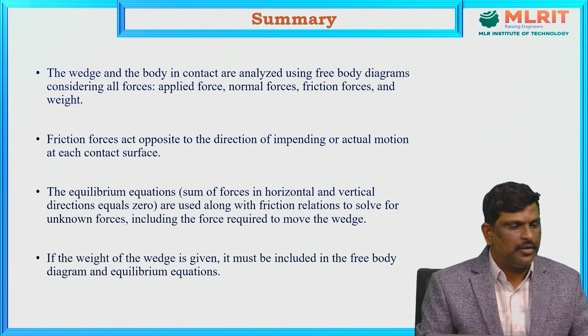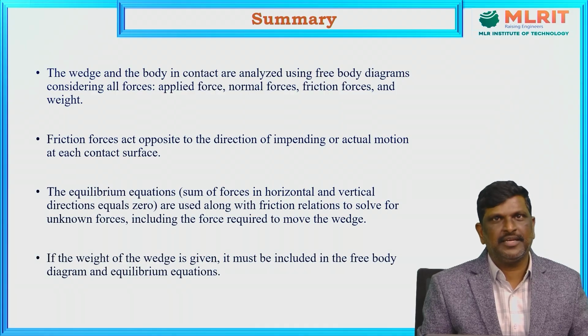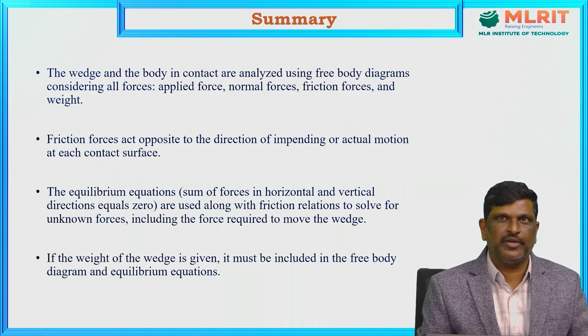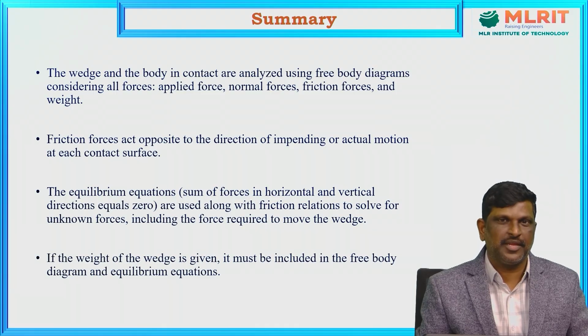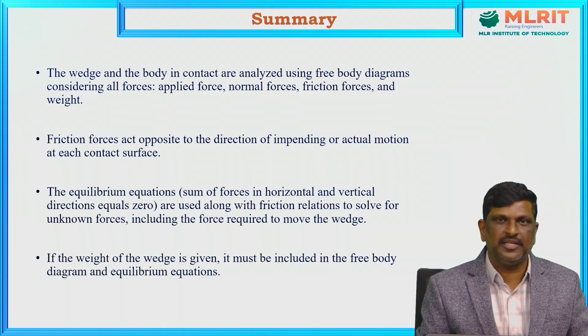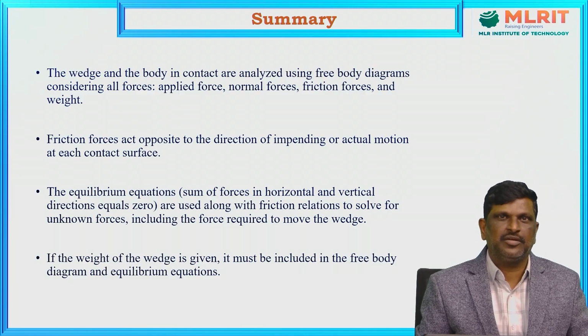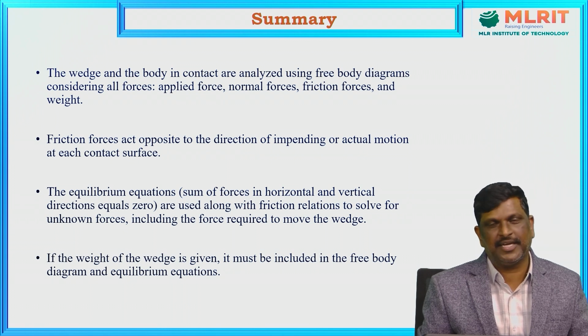Now, the key points to remember while solving wedge problems are: the wedge and the body in contact are analyzed using free body diagrams, considering all forces: applied force, normal forces, frictional forces, and the weights. If the weight of the wedge is given, we need to consider the weight of the wedge also in the free body diagram of the wedge. Friction forces act opposite to the direction of impending motion or actual motion at the contact surfaces.